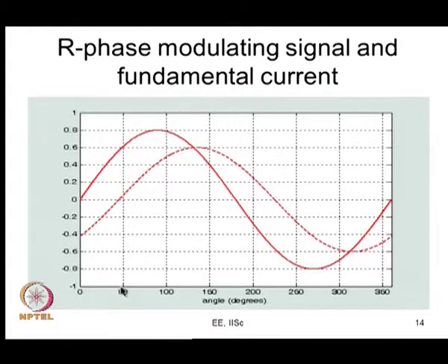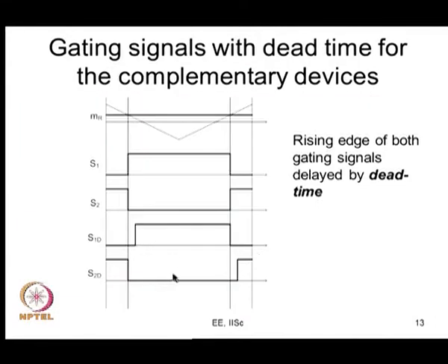But that will lead to one consequence. What is that? If you are considering the smooth sinusoidal current, the fundamental component alone, the zero crossing is very crisp. On the other hand, there is ripple on top of it, around that. What will happen is sometimes you will have multiple zero crossings. So, this could make some significant difference. We normally assume, as I just mentioned, that in a subcycle, as we did in the discussions in the last class and will be doing again today, the current direction is always positive or always negative. It is never going through 0, but it could go through 0. Sometimes it can also go through multiple zeros.